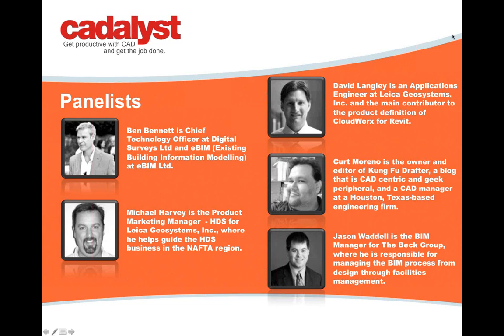Sure, I can help answer that. All of the projects that I work with, I model in state plane. We don't do a project that's not in state plane, just because civil is obviously modeling in state plane. If we model in state plane, for energy analysis, there are so many benefits. Plus, any government agency wants their models in state plane. So if we use consultants to do our laser scanning, we just tell them we need them set up in state plane. They go find coordinates on site. And obviously, like you said, the state plane coordinates are huge. The numbers are in the millions. If the scans are registered in state plane, you bring them in, even if they're pieces and parts of the scans, and they fall right in the exact same place in the model, right on top of it. It's actually very nice and works out perfectly.